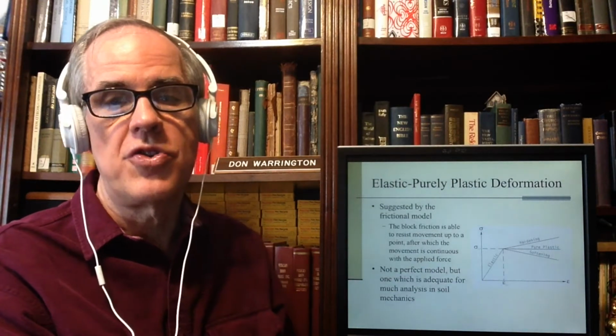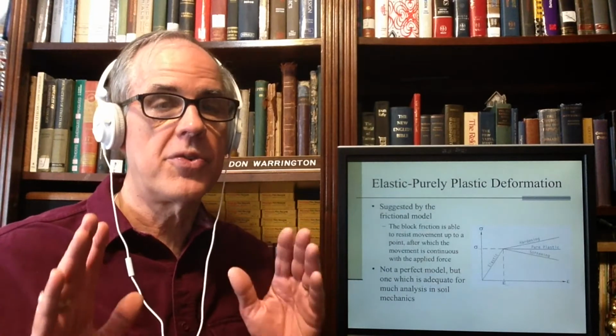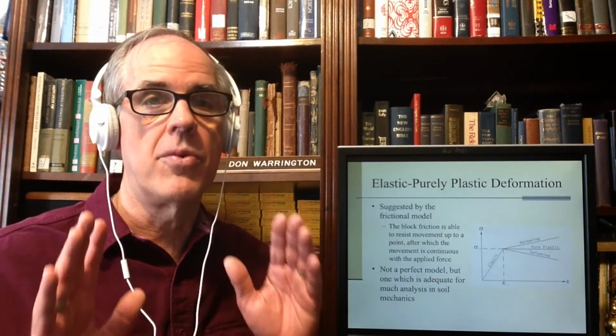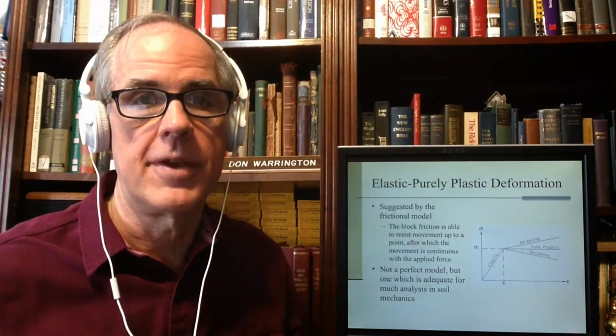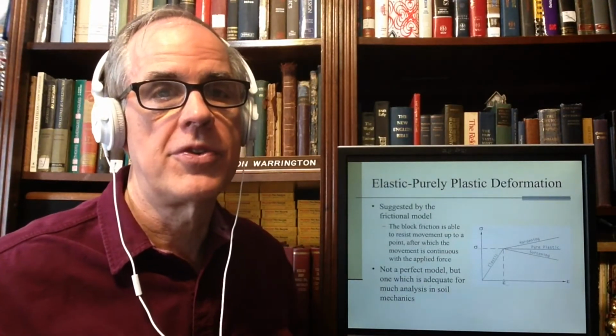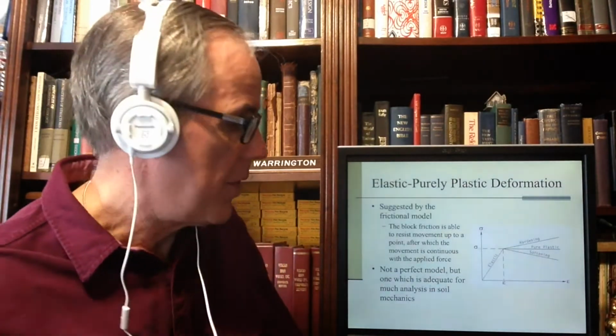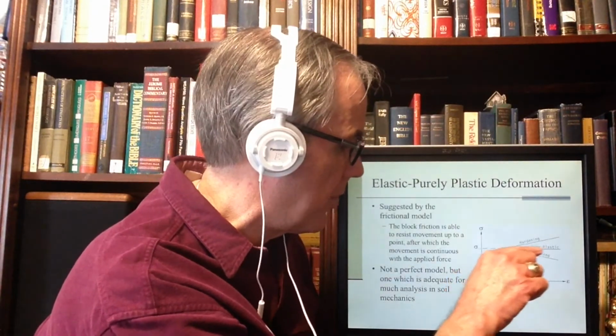But for purposes of this course and the next, we're going to assume Mohr-Coulomb failure with an elastic, purely plastic deformation model. We're going to assume that when we start stressing the soil, we do it elastically to a point, even though the soil actually does more like this.